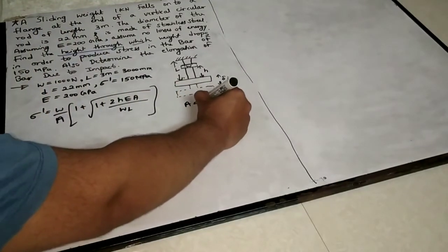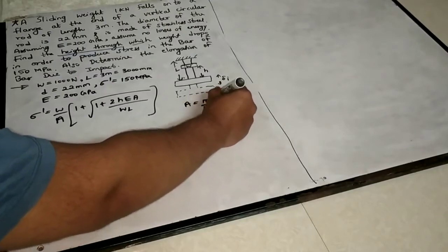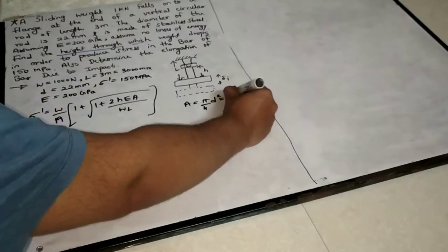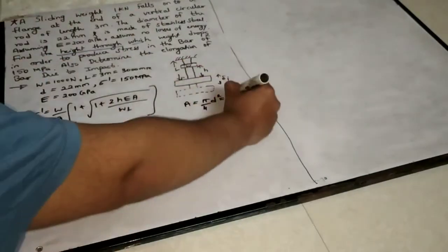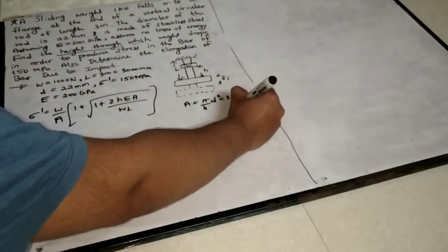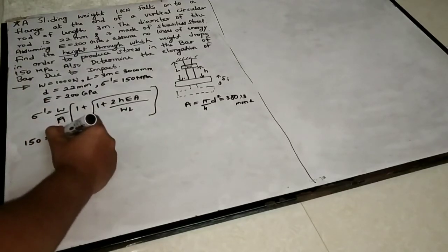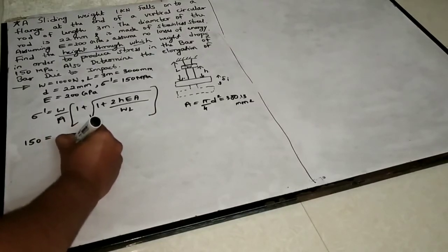Cross-sectional area is pi by 4 d square. So d is 22. If you substitute 22 square, you'll be getting 380.13 mm square. So this also we will substitute. All the data is known to you. So substitute in this. So 150 equal to 1000 divided by 380.13,